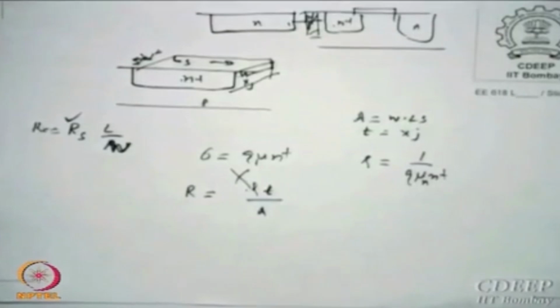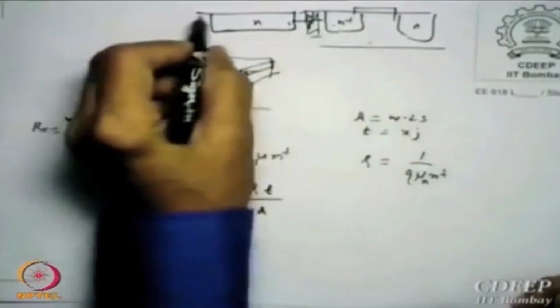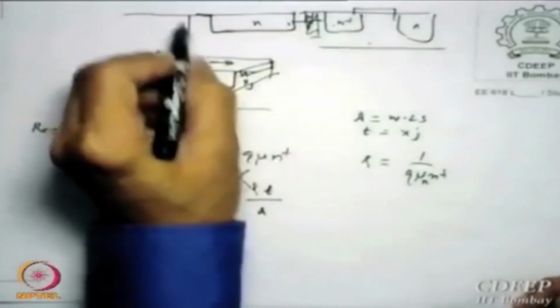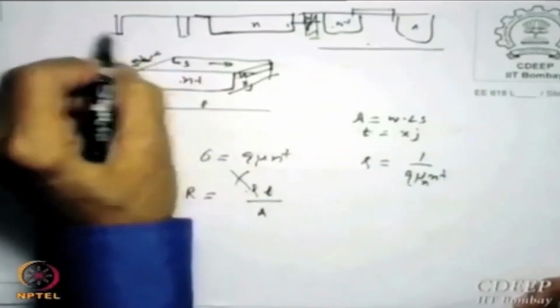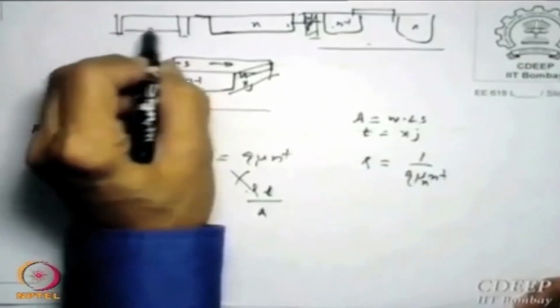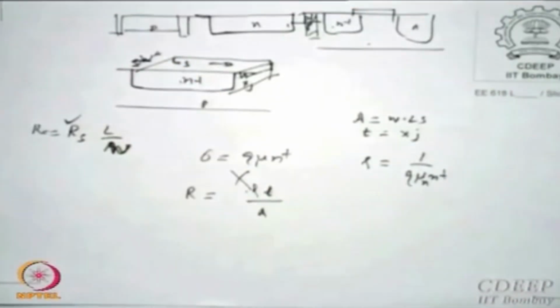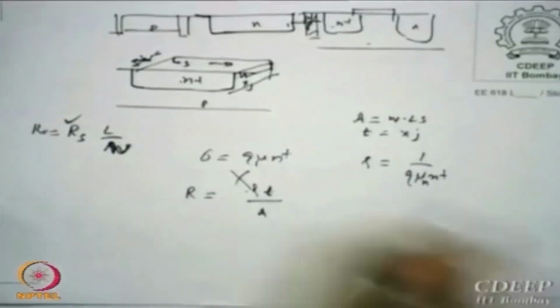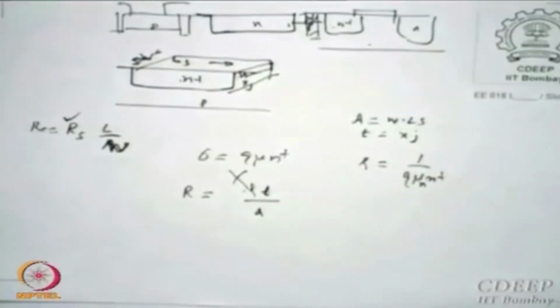Which is the higher resistance if I want, what should I use, which area should I use? N plus is a very low resistance because N plus is a higher doped region, so conductivity is higher. So which area should I use? P region. So I have another separation, and in this P region I have another P created in the P, which has the sheet resistance of my choice, and then make a contact here to make higher resistances.